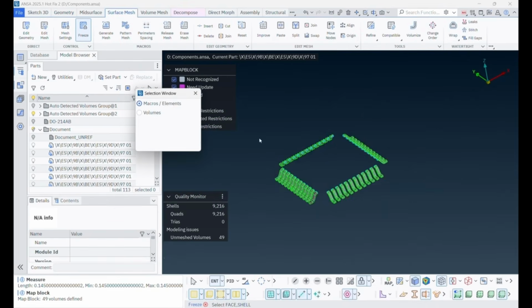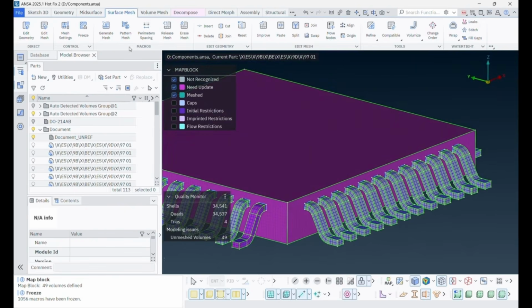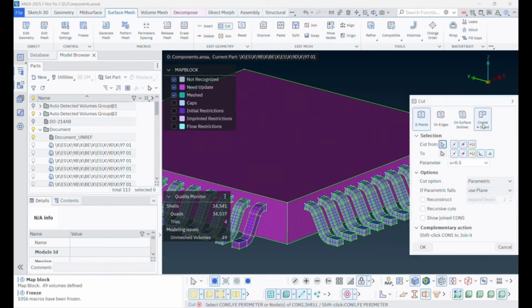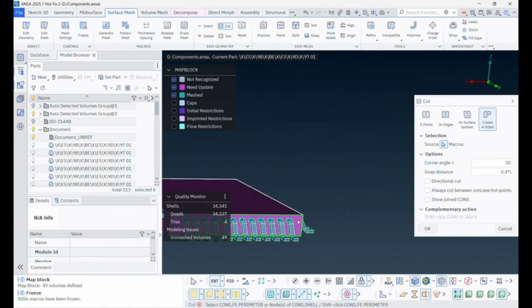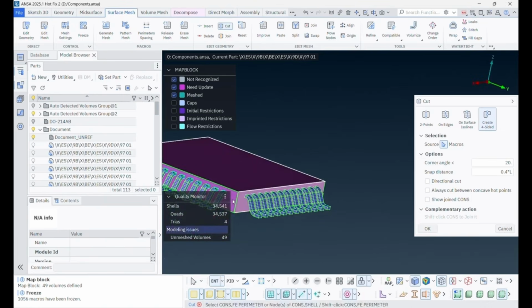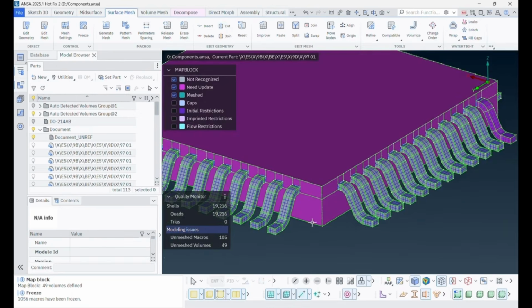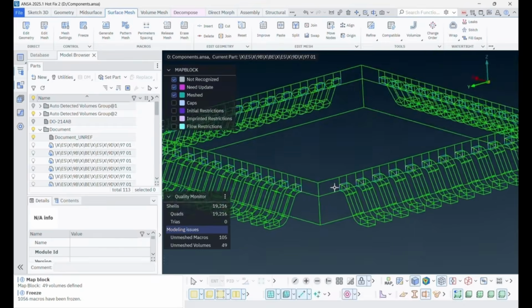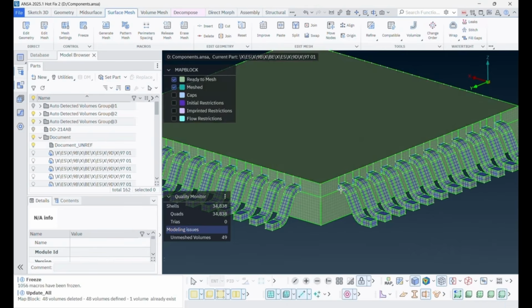Then freeze the mesh in the pin region before processing the 4 large faces connected to the pins. Use Cut and Create 4-sided to organize these areas into 4-sided regions that are more suitable for mapping. At this point, the subsequent mesh quality will be much more stable. After update, the entire model is ready to mesh, allowing the solid mesh to be generated in one step.